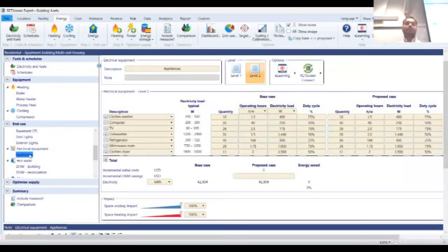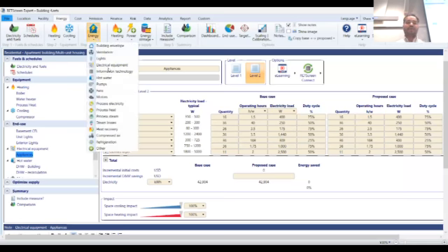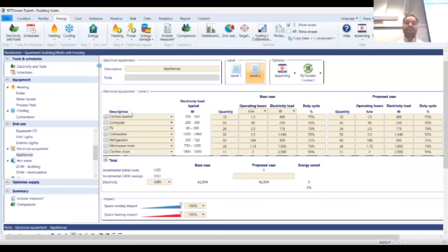Next, looking into the plug loads, like what are the kitchen appliances that might be there. That is something that we have defined. You go into the energy tab, go into the electrical equipment, and that is the place where you can define all the kitchen appliances that you could have for your property. That is something that we have defined out here.